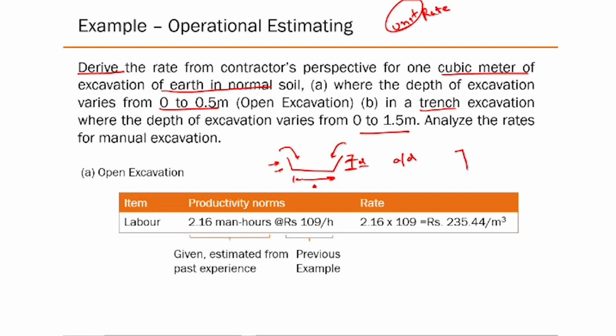So the trench soil or trench based excavation usually requires some sort of a profile. It's a little bit more complex profile than a normal excavation. Now you may need to put some sort of soil stabilization material. Either you put a slurry or something, or you might even put some sort of formwork here, or anchor bolts and things like that to keep the soil from caving. Right? So this is slightly more complicated.